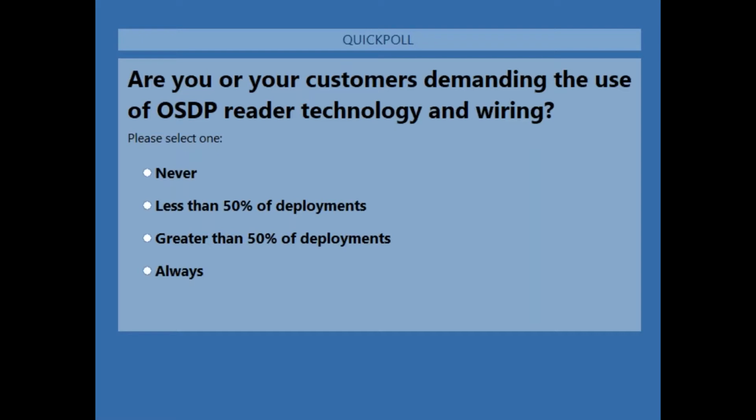Now, if you're going to use just one OSDP reader per reader port, which is what we suggest, then you don't need to change anything, either for HID, Avigilon, or any other. You should be fine, because by default they all come in with address 0, which is the same address that ACM will read just fine. Okay, so keep that in mind.